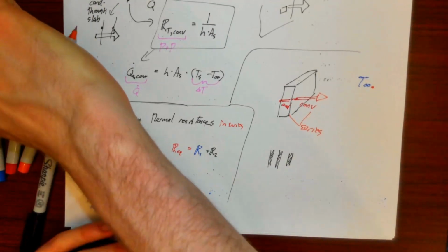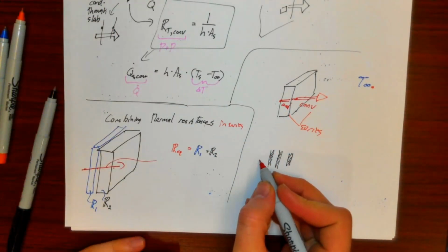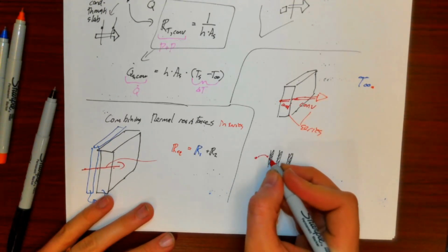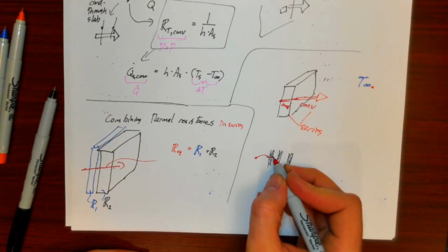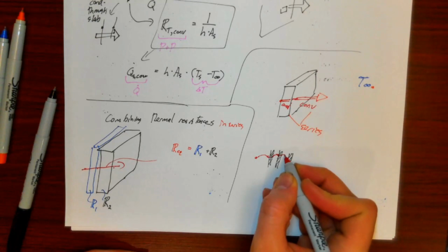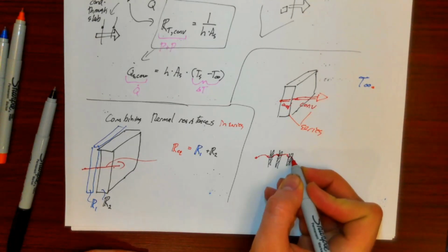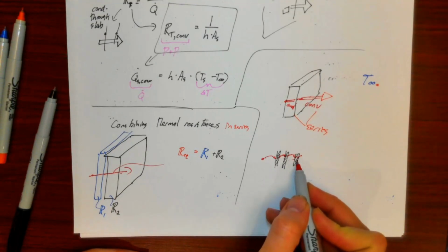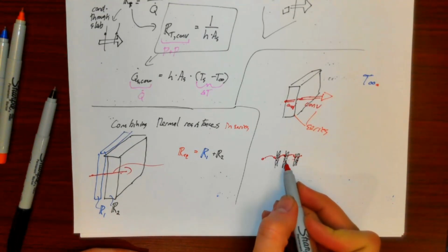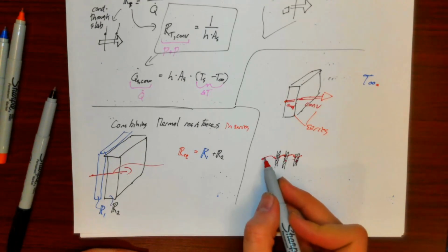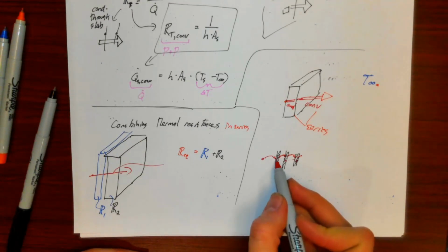And basically what happens is you have a thermal resistance due to convection to go from the ambient air in your room to this surface, resistance due to conduction, resistance due to convection, another resistance due to convection on this side, conduction, convection, convection, conduction, convection, and then we're outside. So having multiple panes of glass not just adds the thermal resistance of the glass, but also needing to convect between the gas and the surface, right?